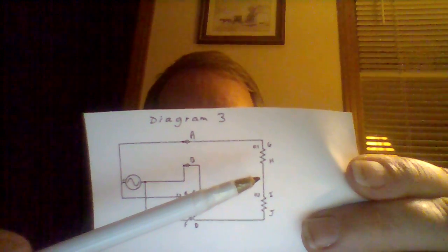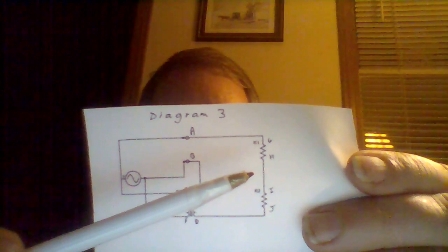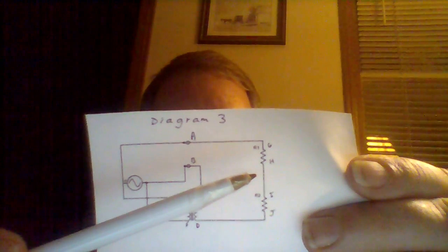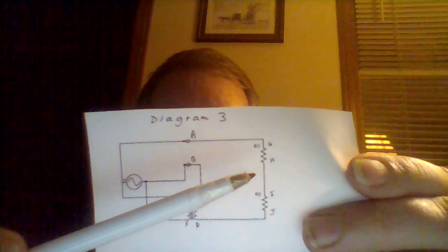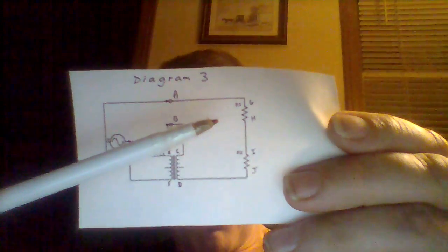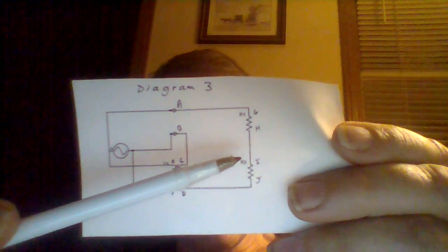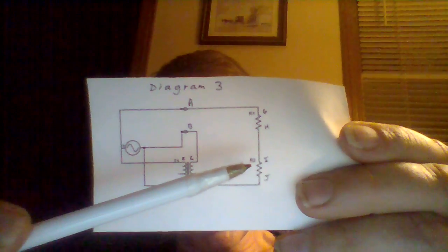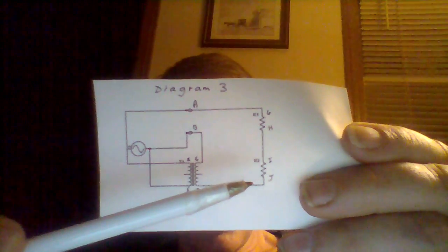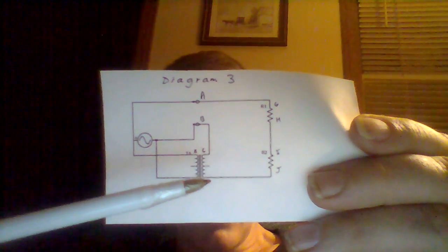And it goes through here. But now we still have another 120 volts because we got 240 volts in total. And that extra 120 volts will drop over there. And when it drops over R2, it pushes that current, 833 milliamps, through R2. And then it goes over here to, I guess you could call that neutral.